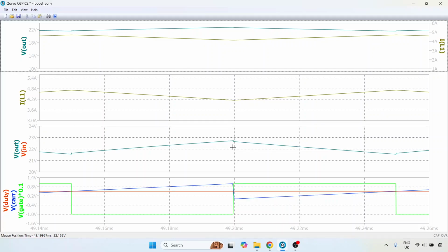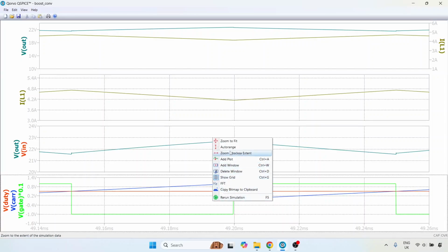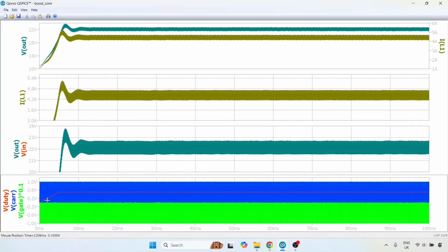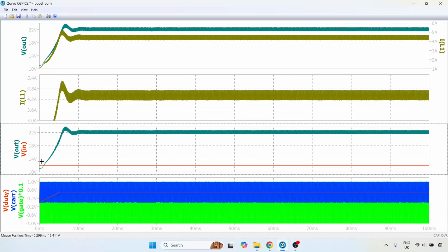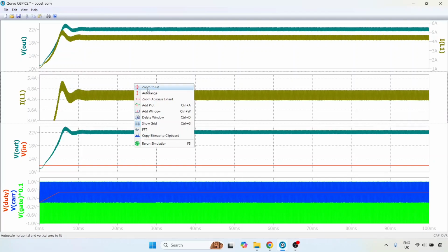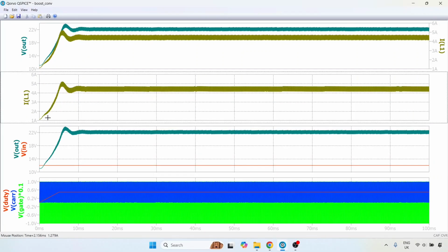and that issue is with respect to the startup time. Let me just zoom in again, and you'll see here that we had raised the duty ratio from 0 to 0.5 rather than applying 0.5 directly. We had seen this also when we were simulating the buck converter, and we saw that introducing such a ramp in the duty ratio results in lesser initial transients. And you see, there are no initial transients, at least there is no current going completely out of bounds.